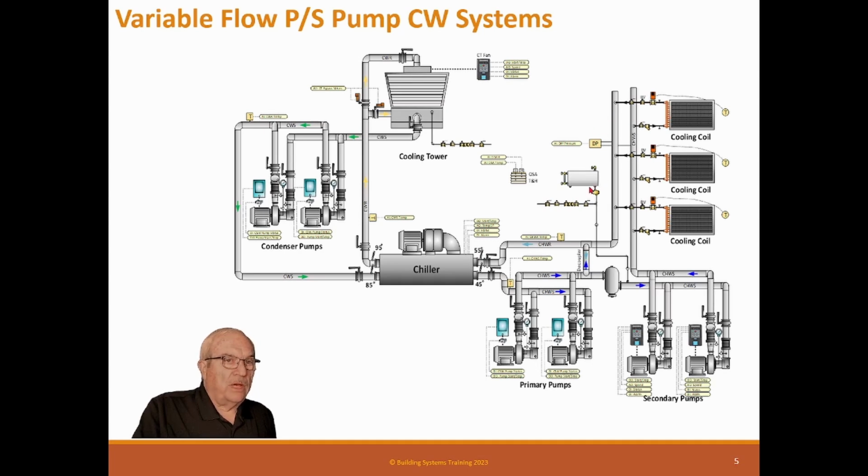So this is why we check, as a balance guy, you always need to check this pressure to make sure it's right. And of course, you take the height from here all the way to here and add a few feet, divide by 2.31, and that's the minimum setting PSI that this could be. So that's really important to do.